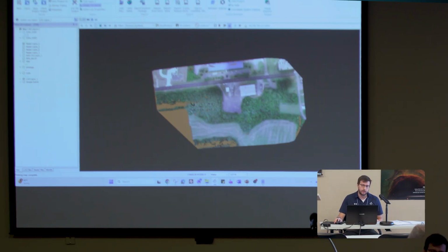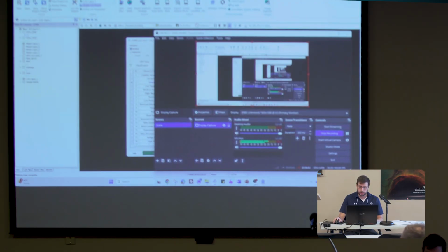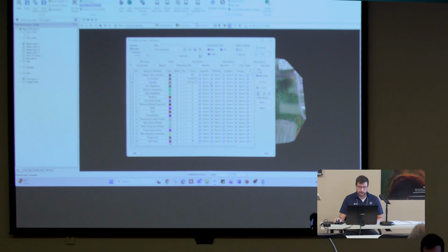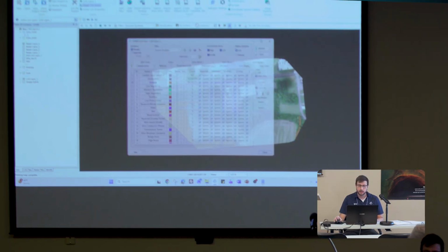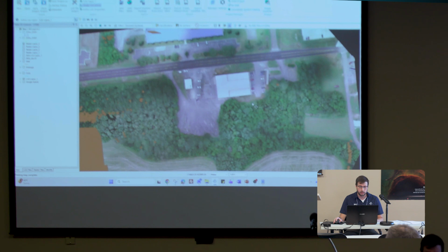So you're not going to be able to create a LandXML with a really hyper dense data set. I'm going to click on the live view filter here at the top, and then I'm just going to do a quick scan of the data. We've got, I don't know, this is well over 100 million points, maybe 150 million points. There's no way you're going to make a LandXML file based on all these points. Even just the ground points, which is typically what you would do, there's no way you're going to be able to do 50 million points there. So what we need to do first is thin the data so we can reduce it to an appropriate amount so we can actually make a LandXML file.